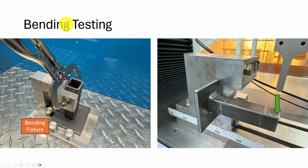Now then, here's a bending fixture where we can come in here and tack this up, and then maybe we're going to slide that sample in here where we could now come in here and push on the end. And maybe we want to look at, is it better to weld on the top and the bottom, or is it better to weld on the two sides? Now somebody's going to say, well, just weld all the way around. The problem with that is deposition, time to manufacture that part. If just two welds would hold that part, that's all we want to do. We don't want to weld all around unless it's just cosmetic and the customer's going to pay for that.